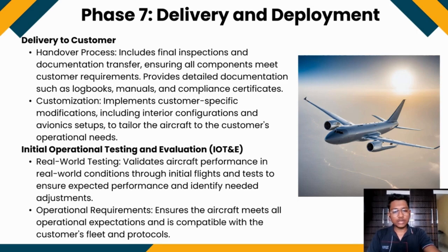Initial operational testing and evaluation, in short form IOT&E, includes real-world testing and operational requirements. Real-world testing validates aircraft performance in real-world conditions through initial flight tests to ensure expected performance and identify needed adjustments. Operational requirements ensure the aircraft meets all operational requirements and compatibility with the customer's fleet and protocol.